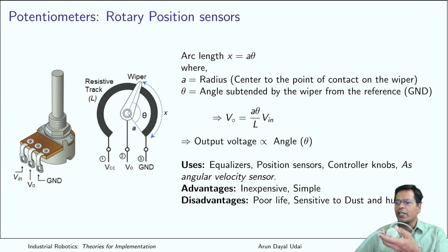You can quickly identify this by counting the number of wires. One is for the shielding, that is system earth, and then it remains with just 3 wires. One is ground, the other one is voltage, and one of them is signal. That's all. So 3 wires and done.